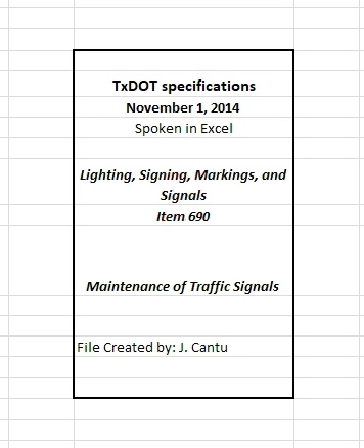4.8 Down guy. Install, replace, remove, or modify down guy with guard or down guy with anchor and guard. 4.9 Steel wire strand. Install, replace, or remove steel wire strand in accordance with Item 625, zinc-coated steel wire strand, as shown on the plans, or as directed. Attach span wire on timber poles using a 5/8 inch straight thimble-eye bolt. Attach span wire on metal poles using at least 2 turns of wire around the pole. Place and properly tighten the 3-bolt clamp as near as possible to the pole.